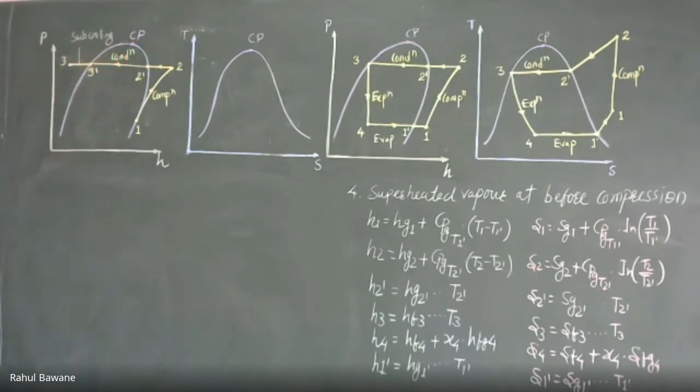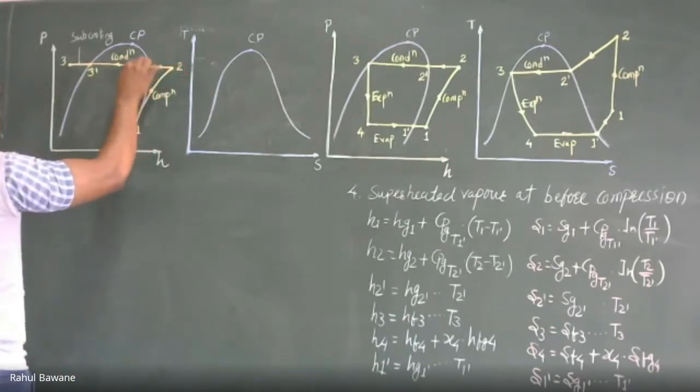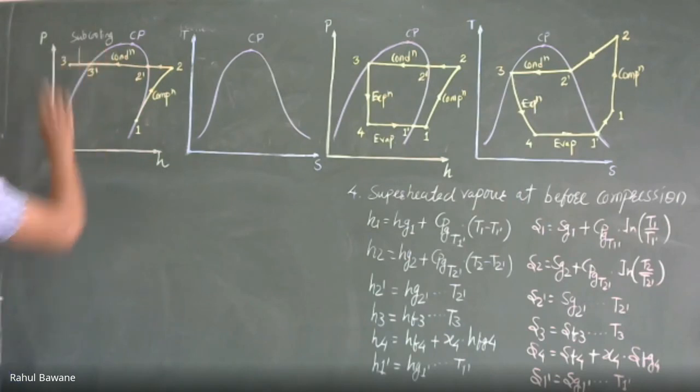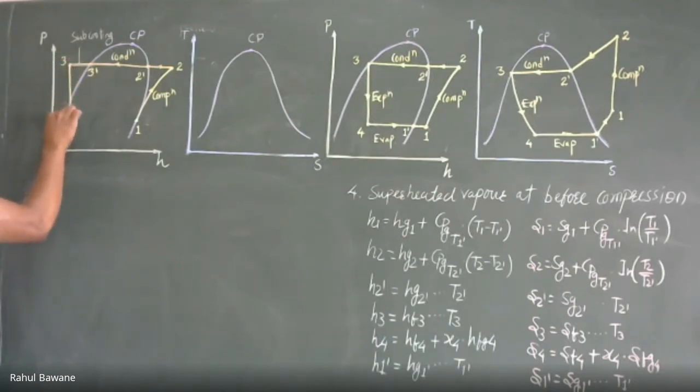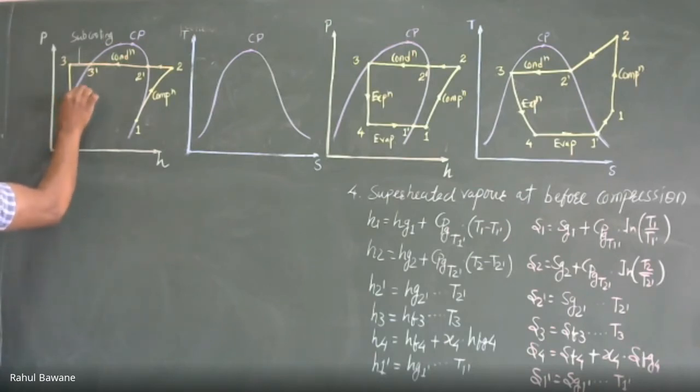It is also called undercooling. So we have cooled down our refrigerant below the saturation condition. But the process is at constant pressure. Pressure is not affected; pressure neither increases nor decreases. So after that condensation, we supply this refrigerant to the expansion valve where a constant enthalpy pressure reduction process takes place. So this is constant enthalpy pressure reduction. So the expansion process is there.